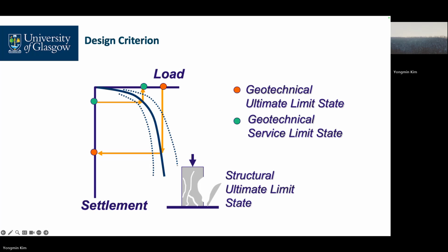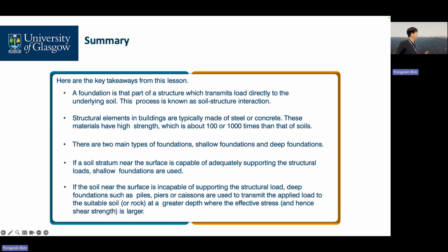Then two criteria, right? Serviceability: your pile shouldn't exceed certain settlements, and ultimately your bearing capacity. Then we don't worry about structural ultimate limit states because our pile material is strong enough. Okay, this is the summary.